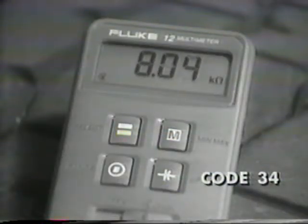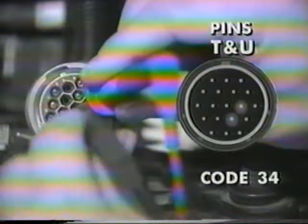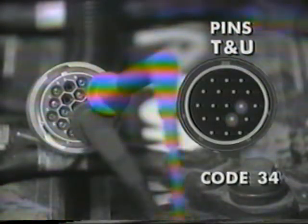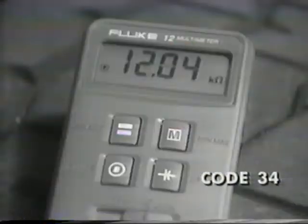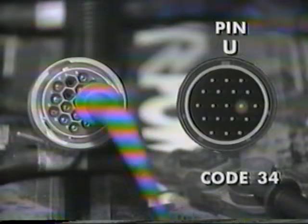Resistance should increase smoothly with no skips or jumps. With the probes between pins T and U, move the throttle slowly again. Resistance should decrease smoothly. The resistance between pin U and ground should be open. If the readings are okay, both the sensor and wiring harness are okay, and the shift bar cover is faulty, replace it.